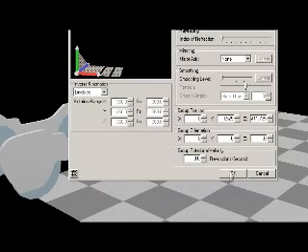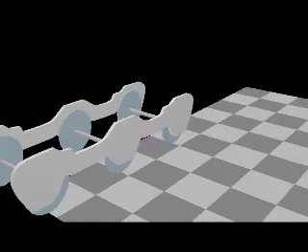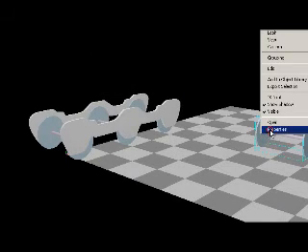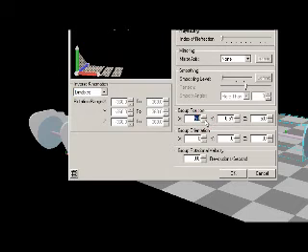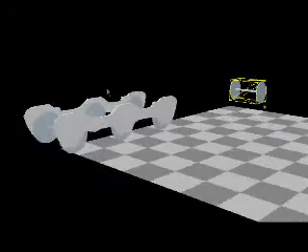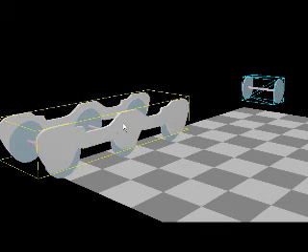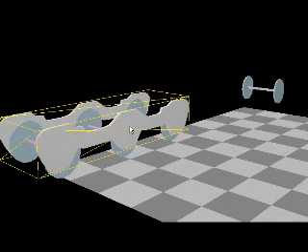and the Z will be 11.735, which is the distance between the two center wheels. We have an X position of 0, a Y of 0.525, and a Z of 11.735. Now that's the center wheel, and using that information we can make a copy of the bogies.